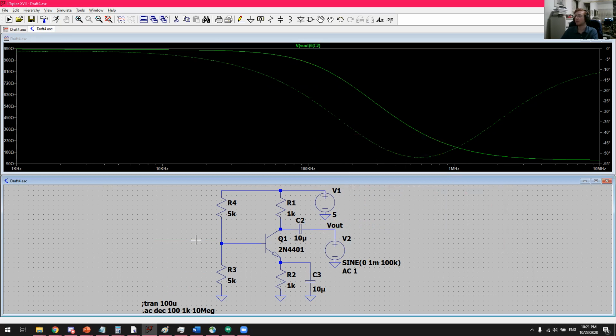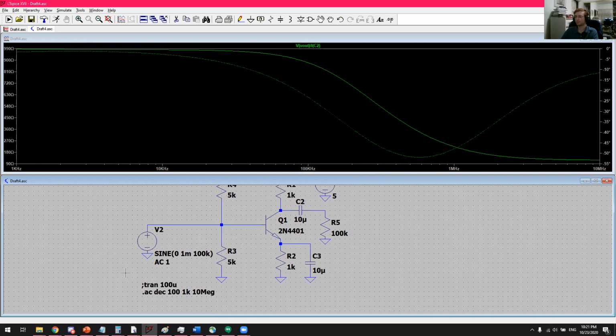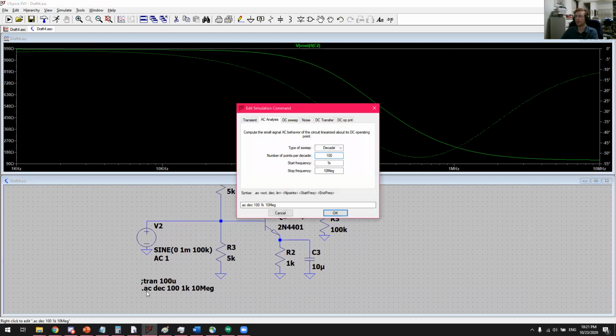So anyway, what we did is we took away the input, we fed in a signal into the output and measured the voltage divided by the current, which should get us the resistance. So this is about 880 ohms, right? So let me put this back on the input. Connect it back up. And put the resistor back in. And let me disable the AC analysis.